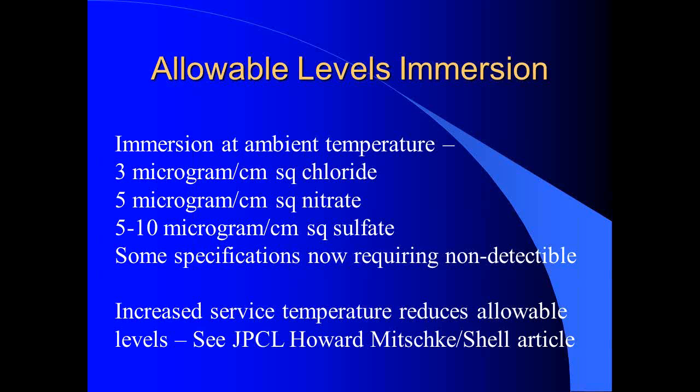The other thing is increased service temperatures reduce the allowable levels. There's a JPCL article by Howard Mitschke, who worked for Shell Research. If you go on Paint Square, you can research Howard Mitschke, the article, or even salt articles, and it'll come up. What he found out using a 2-coat epoxy system for tank linings at ambient service was that if he had anything more than 3 micrograms per square centimeter, they failed prematurely.